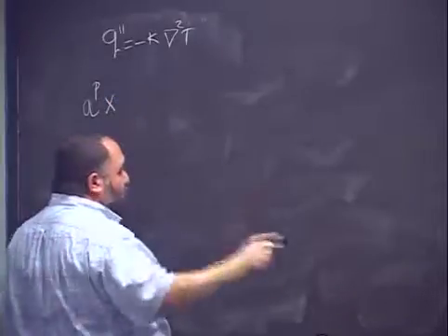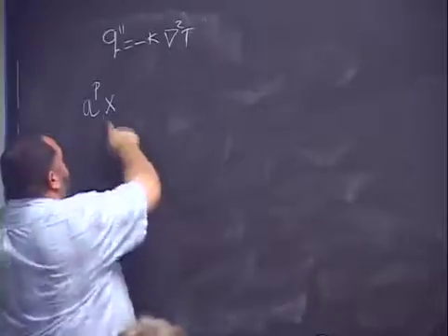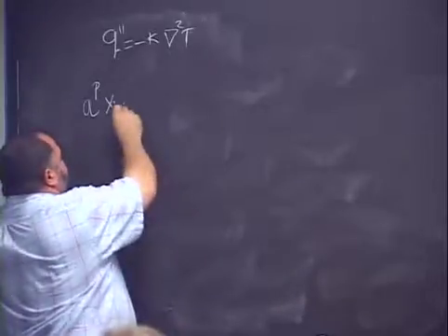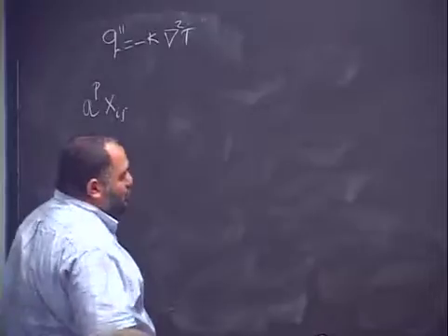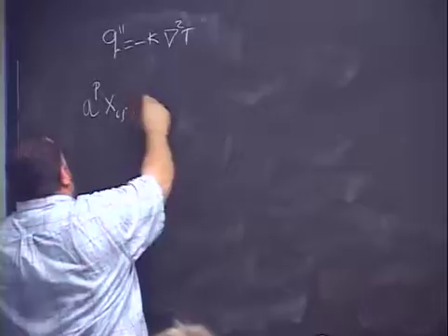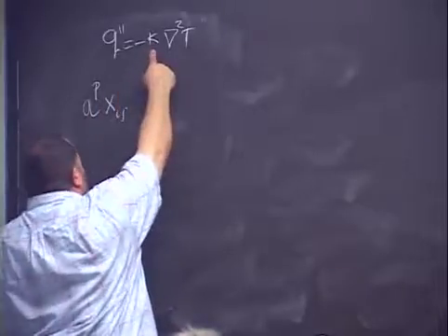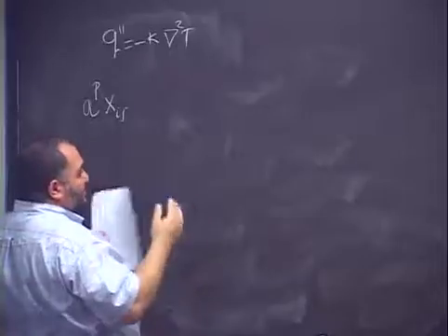Each one of those nodes has a temperature defined at it. So x i j will be the temperature at the node i j. A P is the coefficient here, which will be the heat conductivity multiplied by a constant or something like this.